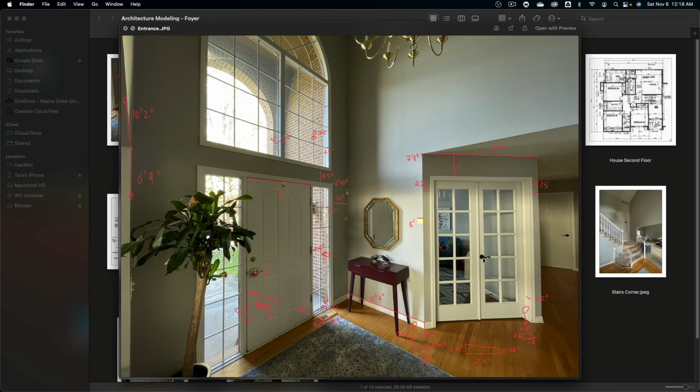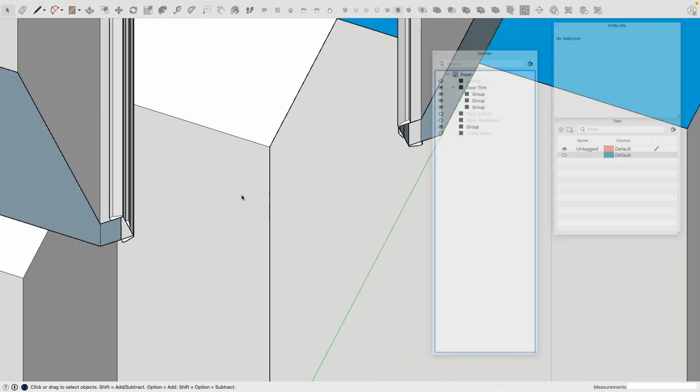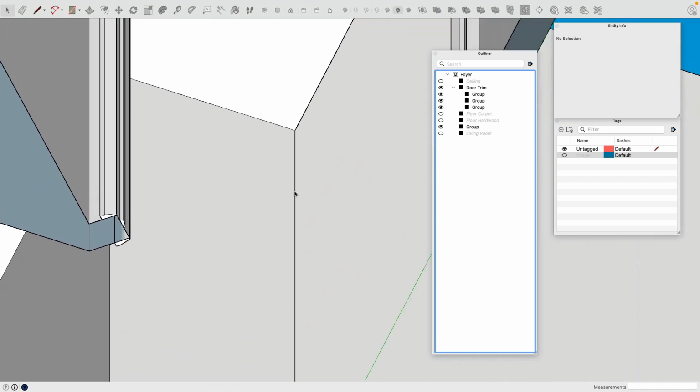When we go back to the photo, there's quite an offset, and then the door goes up. We will also create these pockets in there, but without all that trim work, we do this more nice and cleaned up. We will draw a rectangle at the ground, find the midpoint, and draw a door up. In this exercise, we make the doors razor sharp fitting in so they can't rotate. For render purposes, that's totally fine. Then we add a little bit of distance at the bottom. So how do we start now?